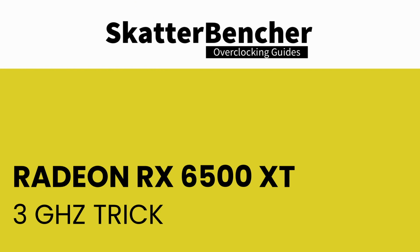Before we move on to the overclocking settings and the performance, I want to show you one more neat little trick. As I already said, with the ElmorLabs EVC2SX, we can also increase the GPU voltage using a voltage offset. Now, as it turns out, when you increase the GPU voltage, you also increase the GPU frequency. We can use this trick to get our 6500 XT graphics card all the way up to 3 GHz.